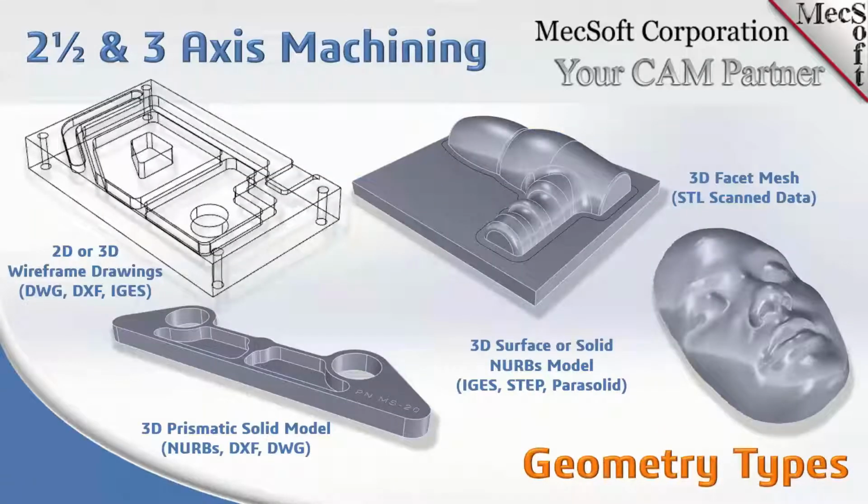Okay, let's talk a little bit about geometry. In our CAM products, you can program tool paths with just lines and curves. Like you may have a wireframe drawing. Typically, wireframe drawings are not used much anymore. But if you had just a 2D drawing, a top view of a part that you needed to machine, you could use that in conjunction with 2.5 axis toolpath methods to machine your part.